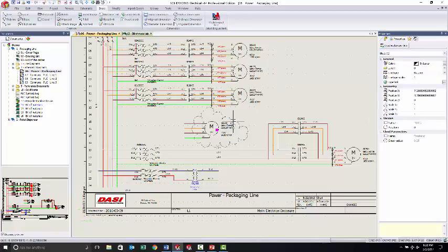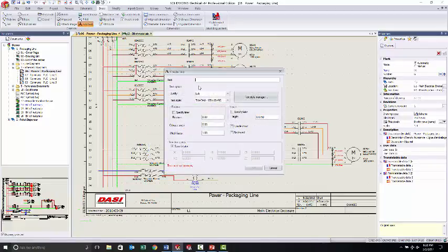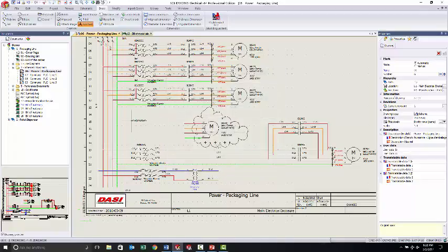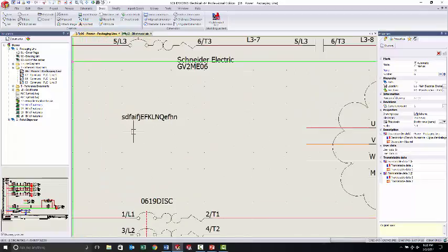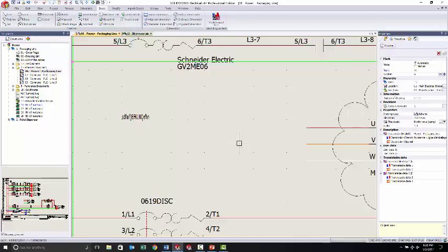You can actually get to more of it even when you're dealing with text, because text is one of the big ones. When you are adding text, the first thing that I've always found is that if it doesn't quite add up to what I'm looking for, maybe this is too large, too small, I can now even get into the width factor so that I can make this narrower if I need it to fit into a specific box.